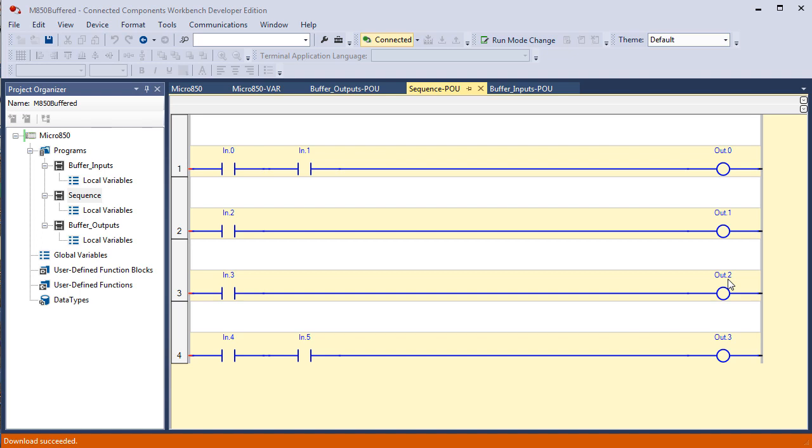We don't have to do that in our code because in OTE it's implied that if the rung in is true, then this turns on that memory location. If the rung in is false, then it turns it off. So the then-else is included as a true to false execution. We just want to do a quick little review of how we left that logic in our last project.